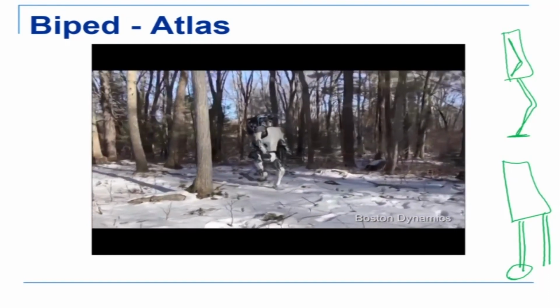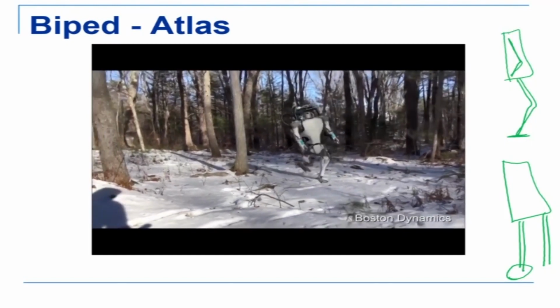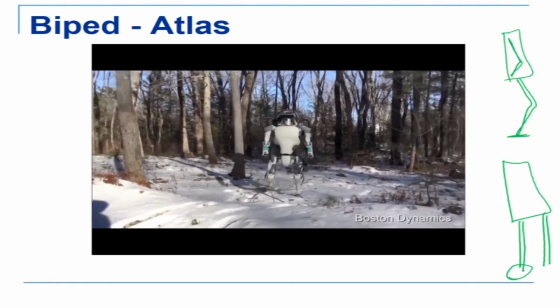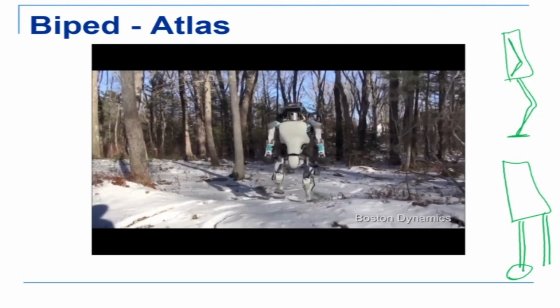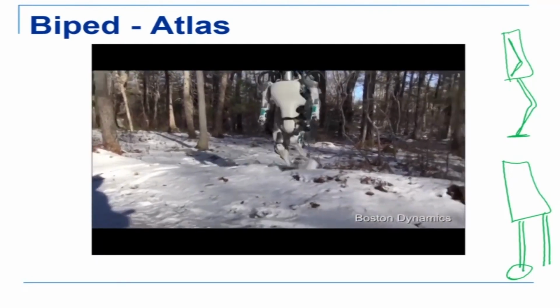Please note that the legs are bent. The robot walks with a bent knee, and that is basically for stability. When we come to stability, I'll explain why it does that. Okay, so look at the shape of the legs and look at how the foot placement is being made. So it is on one leg stance, two leg stance, then one leg stance. And that is exactly what we mean by pattern of foot placement.